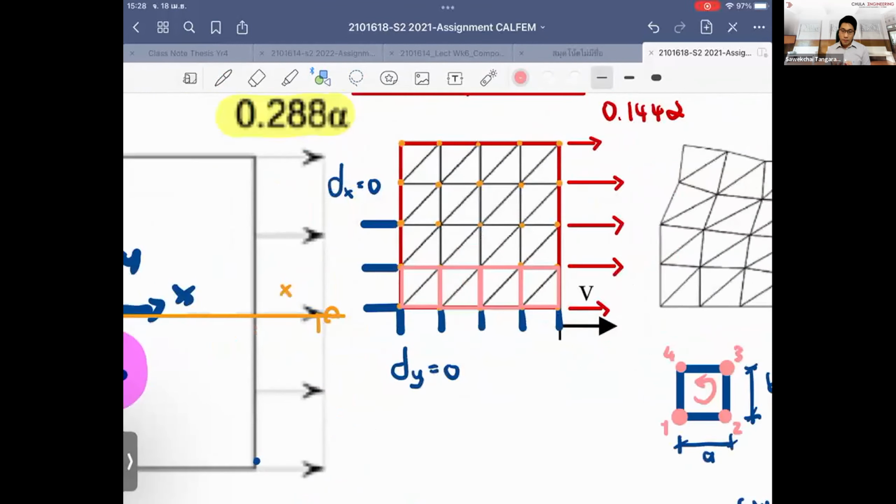So you might see that the pattern when we start to construct the mesh is just repeating. So it means you just keep doing the same routine for all the elements. If you need to have 100,000 elements, it is not possible to do it by hand, right? You have to write some little code to ask the computer to split the elements for you.